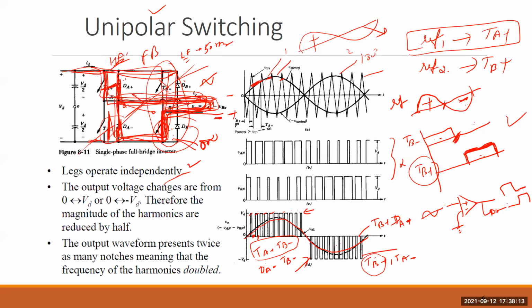And sir, why do we say that circulating current also consumes reactive power? Circulating current mainly consumes reactive power because it is not contributing to the fundamental power, the real power to the output. Fundamental power is the useful power, but the circulating current is not providing power to the output.